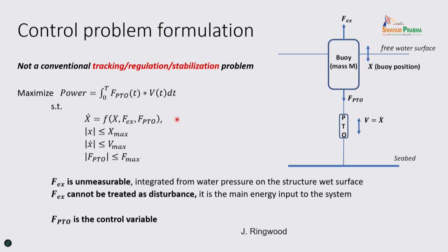If you look into linear quadratic control, people care about the x square and u square. This is the RQ term, and they normally don't care about the cross diagonal term. Here, in wave energy control, the cross diagonal term is more important.